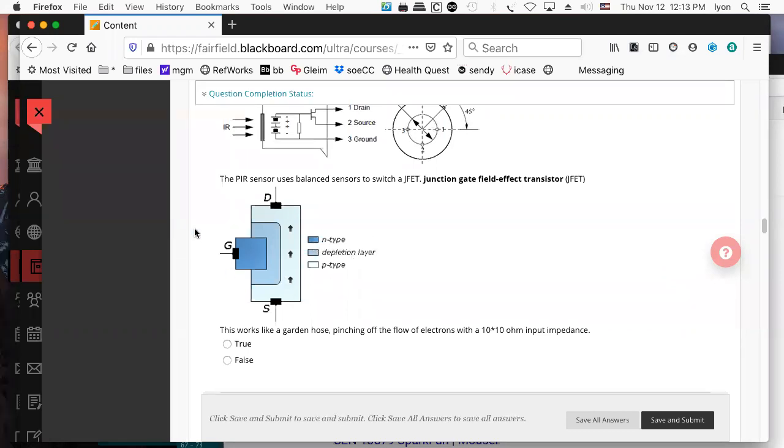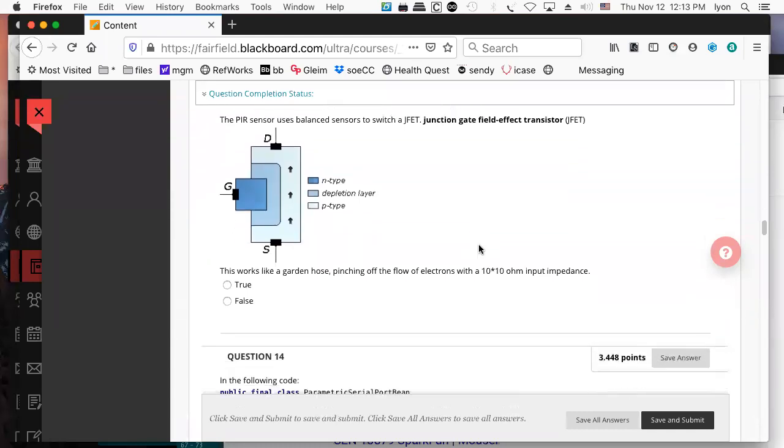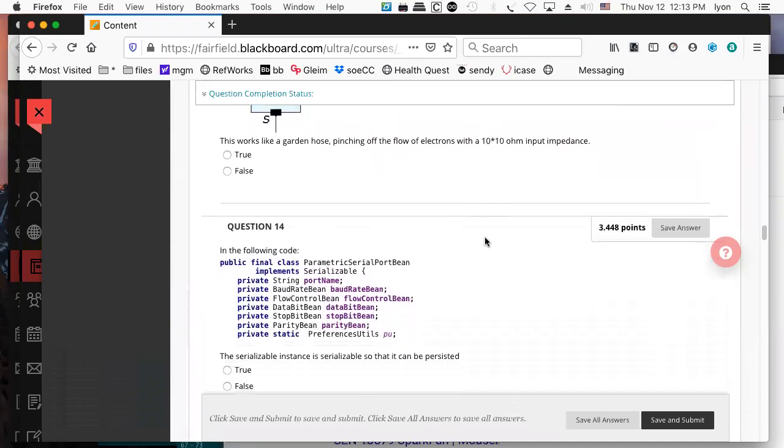It's a mistake to simply say a transistor is a switch. It's not. It's an amplifier. And if you operate it in saturation like we normally do in digital design, it acts like a switch. But if you load down a bipolar junction transistor so that it has to drive too many inputs, like more than 10, it will act in funny nonlinear ways. It won't operate in saturation. It won't just go on or off. It'll start to act more like an amplifier. And you have to watch that sort of thing.